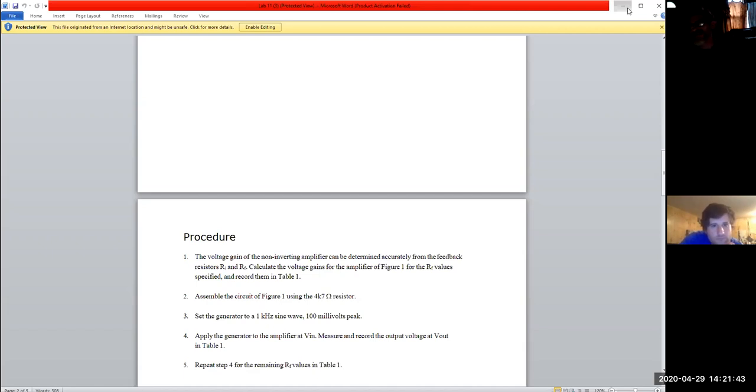Or in a case like the Zeners, right, where we're going for voltage references. And you'll find those used. The one drawback with using a Zener is that you can get the voltage, you just have no kick for it, so you don't have any current involved. A lot of times what you'll see is on DC power supplies. And in fact, this is such a crazy way to save some money, right? A lot of these DC power supplies in warehouses and factories go bad. The reason being is that they'll have a Zener in there, let's say you've got a 5-volt DC power supply being used somewhere in the plant, right?